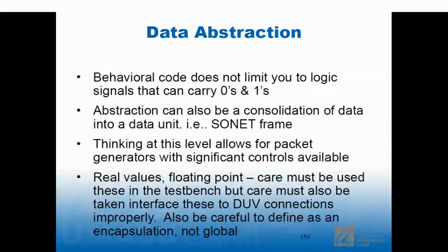So what could go wrong in that? Well, a lot of stuff could go wrong, right? I could have mistakes in the state machine. I could have addressing that isn't quite right. I could have race conditions. The place where things really go wrong in a pipeline processor is when there are things in the pipeline producing results that things behind them in the pipeline need, but they're not ready in time.